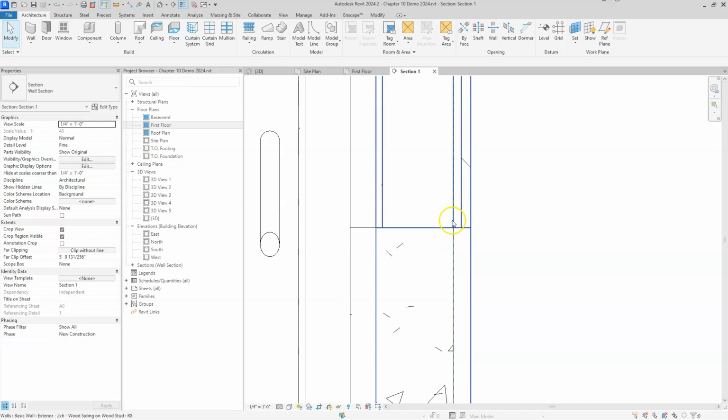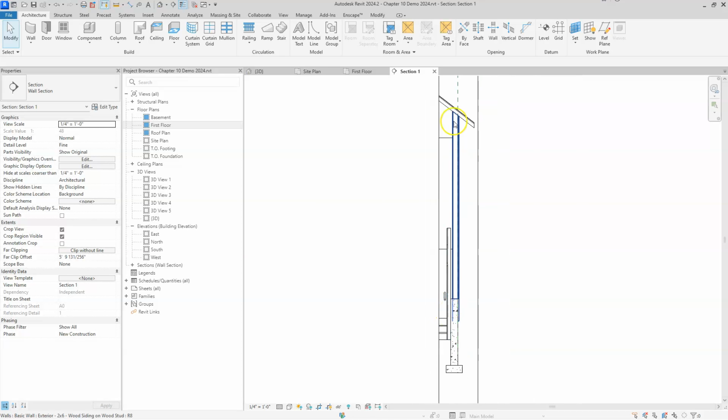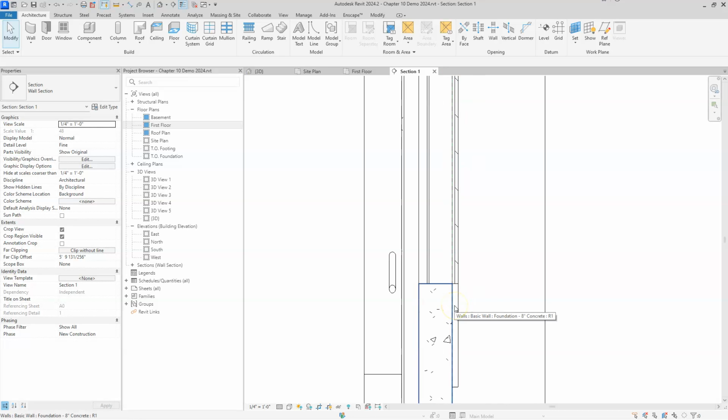They're going to run it all the way out to the edge. The siding and the sheathing hang out beyond that. In fact, in reality, they actually hang down a little bit below the top of the foundation wall. You may recall some discussion about that last semester where we talked about how to prevent air infiltration and water penetration coming into the house. But the reason we're looking at a section view right now, and the reason we're even talking about walls and reference planes, is because that reference plane is also sort of the magic boundary that aligns with the floors.